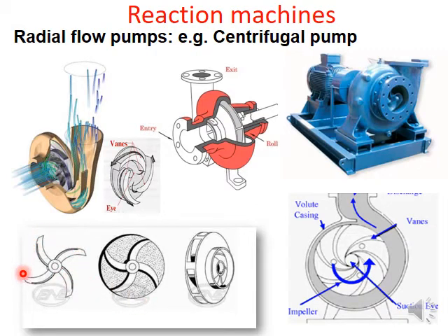If the fluid that you want to pump has debris or impurities, you use what we call clogless or open impellers. Because if there are impurities, debris, sand, or some material, see, there is a possibility of clogging or blocking inside this impeller.